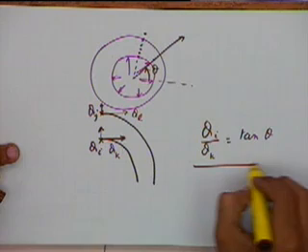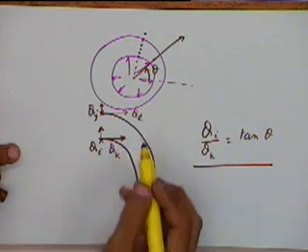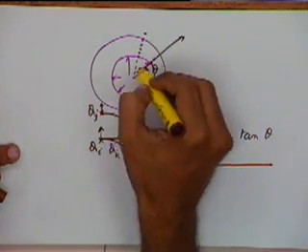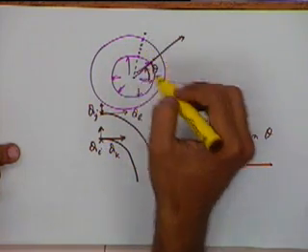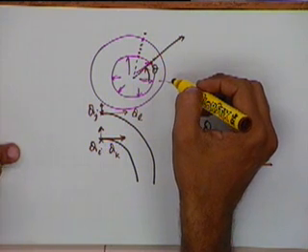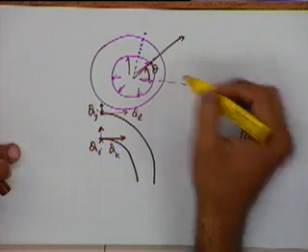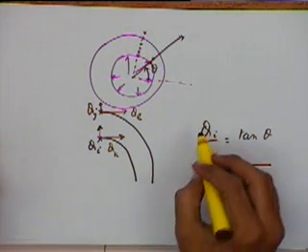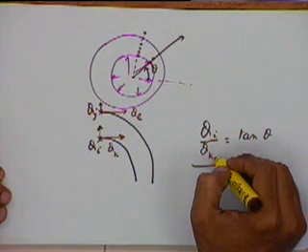So again this is a multi-point boundary condition, because you are basically saying that a node here has to move only in the radial direction. That means the x direction deformation and the y direction deformation have to be related to one another. This is a two dimensional case, not a one dimensional case. So this is also a multi-point boundary condition. Similarly there are a number of situations where deformations of more than one node are constrained together by a linear relationship between them.